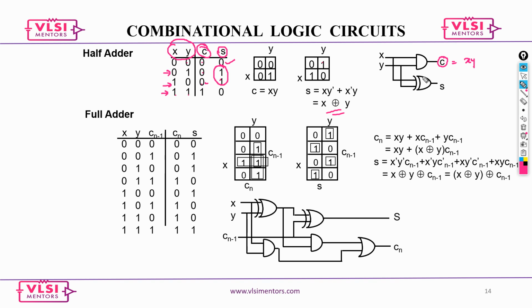Okay, so now you see here this is an AND gate, and say this is an XOR gate. Now this is basically a half adder where we have only two inputs and we don't take any carry in. Now there is another thing that is called a full adder. A full adder means there are two inputs, X and Y, but there is another input called carry in. Here there is a sum and then a carry of that particular stage.